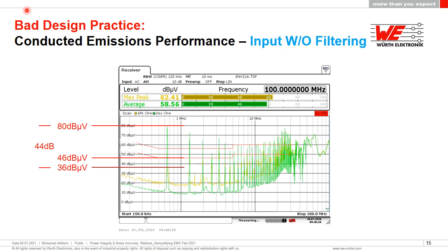plot that main issue that we're seeing here is the switching frequency of the power supply. As we go up in frequency, we will also see that there's going to be quite a substantial component of those high frequency ringing that we saw earlier in the time domain signals. Now, I know some of this could be very much associated with the scope measuring and the scope itself and the way you're measuring on the board, on the PCB.